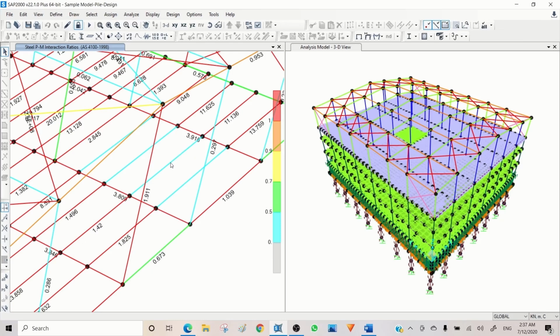At least you can get the reasonable and correct moment and deflection, but you need to design the beam manually yourself. The beams here, yes, if the moments are correct, you may be conservative and design the beam by considering the effect of a slab, but the correct way is using this composite section and design the composite beam, because the result would be different. So this is not very economic. Using the composite section is the right way.